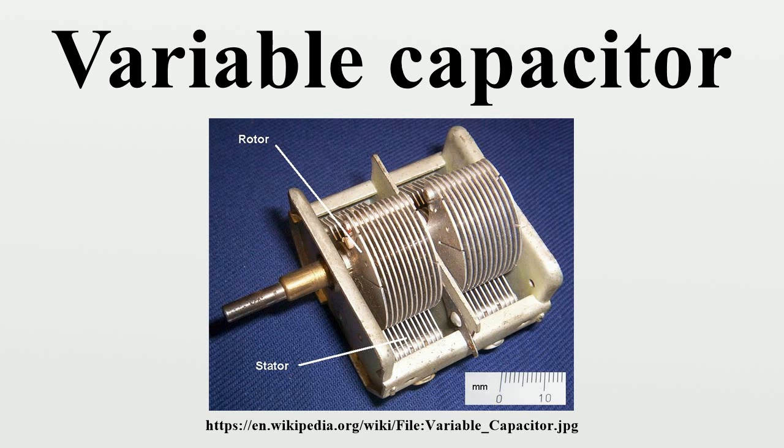Differential variable capacitors also have two independent stators. But unlike in the butterfly capacitor where capacities on both sides increase equally as the rotor is turned, in a differential variable capacitor one section's capacity will increase while the other section's decreases, keeping the stator-to-stator capacitance constant. Differential variable capacitors can therefore be used in capacitive potentiometric circuits.